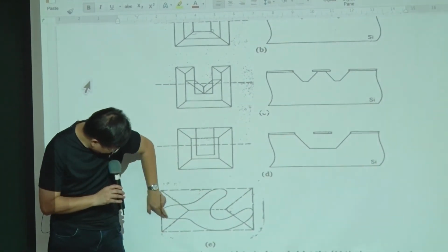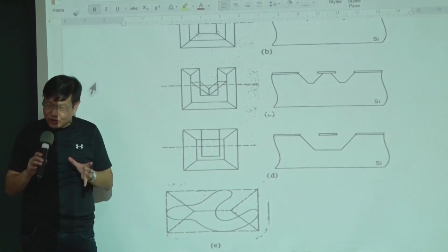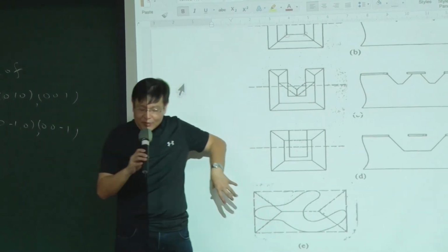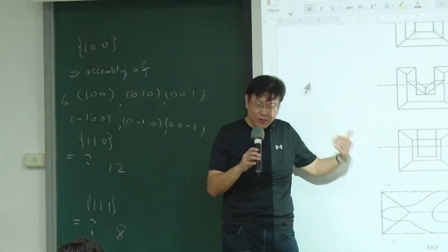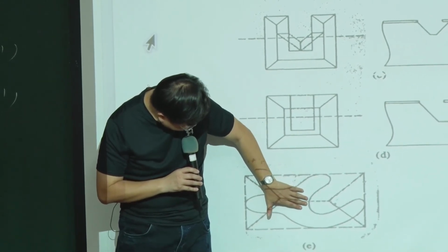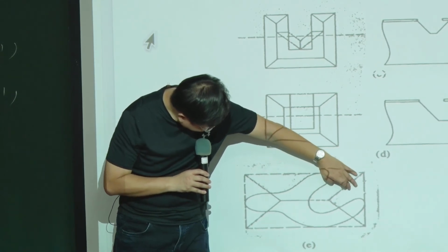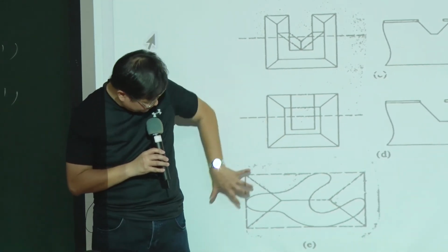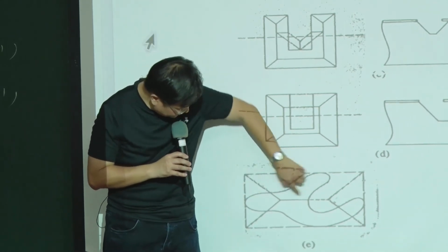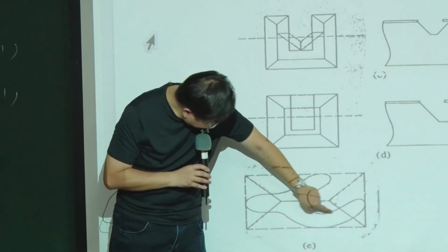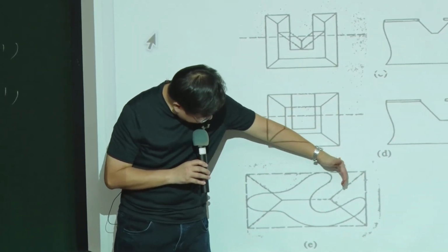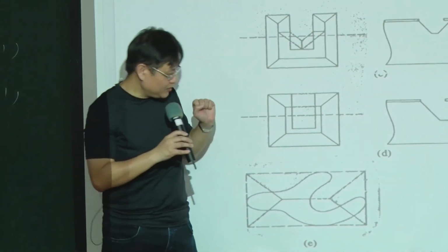So we have a common sense question. If we draw arbitrary structures, holes on the surface, what kind of final shape can we have? Actually, the answer is a pyramid-like structure, because we stop at the 111 surface. For example, you have this kind of opening, so the structure underneath the mask will be retreated until it faces the final 111 surface. Because this is a long structure, we have a pyramid structure with an extension in this direction, the center part extension, like a V groove underneath. The extrusion part, the convex part, will be retreated, and the material underneath will be retreated all the way until it faces the final 111 surface. So an easy way to draw is like this.